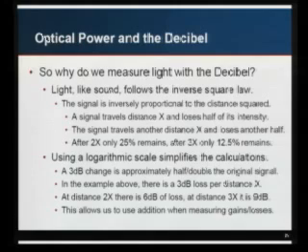And the reason that we use a logarithmic scale is that basically cancels that out. It turns it back into a simple addition problem where you say a 3 dB change is half or double of the signal. So now you say it's 3 dB per distance x. So if you go distance 2x, you can add it. It's another 3 dB. It's another 3 dB. And it makes the math much simpler. That's basically why we use it.